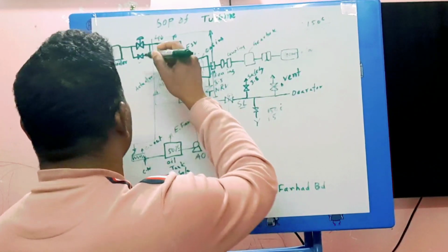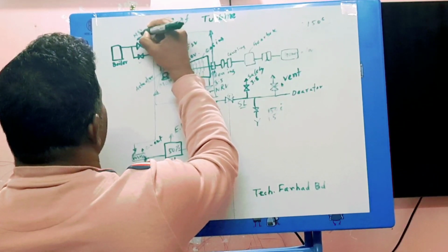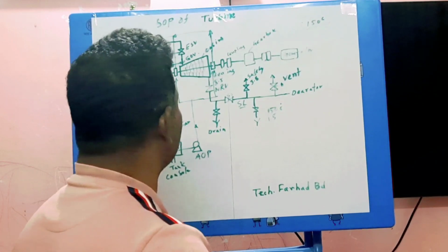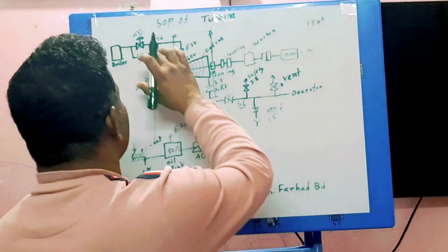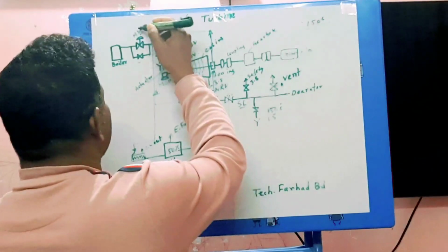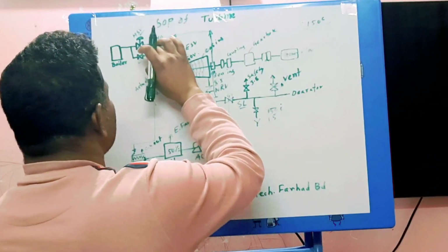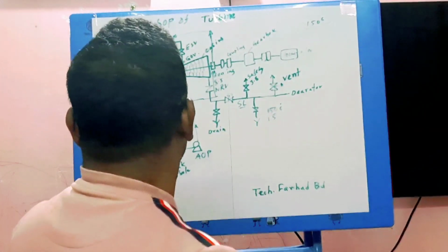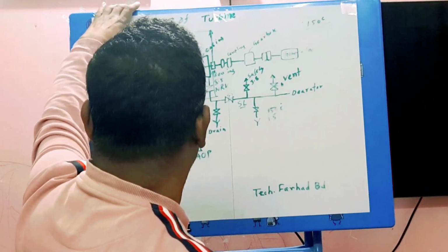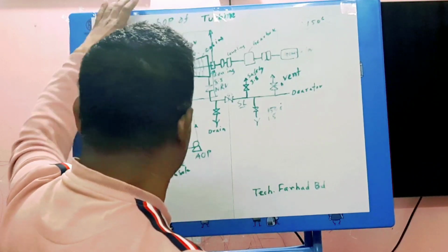For giving this rolling, the main steam valve, called MSV, needs to be opened slowly while checking the RPM. Slowly the main steam valve needs to be fully opened. After fully opening the main steam valve, you then need to close the main steam bypass valve.